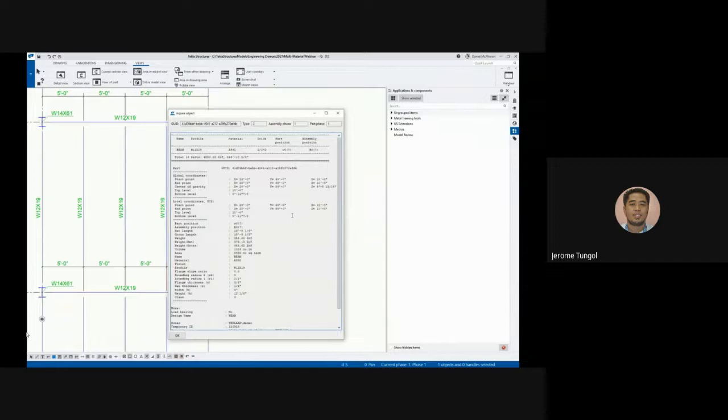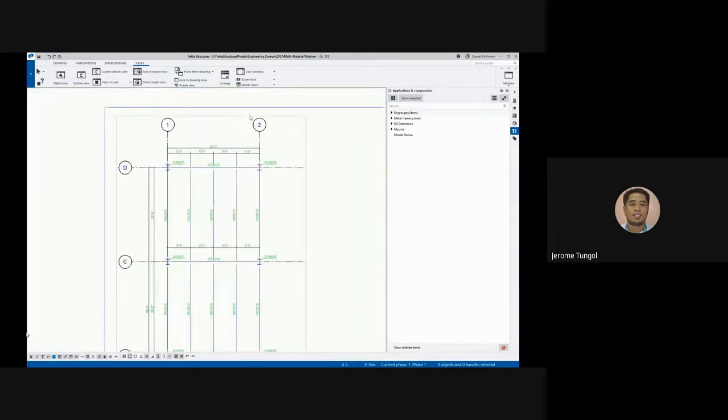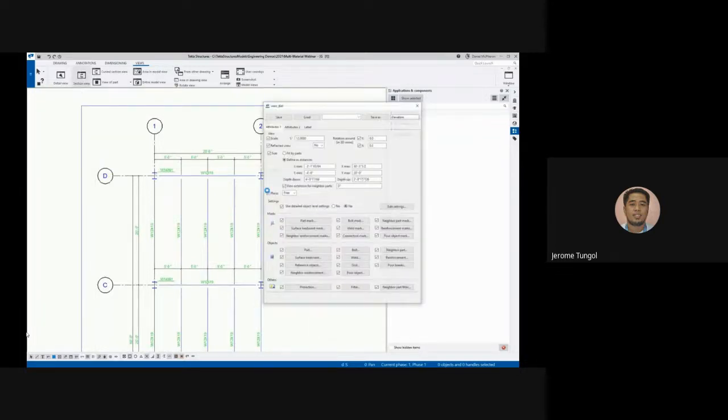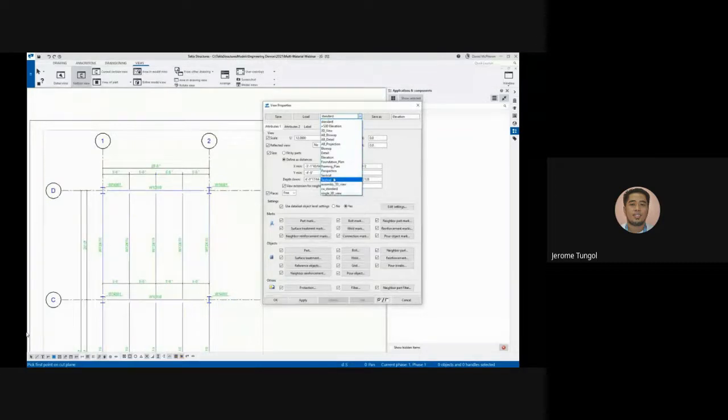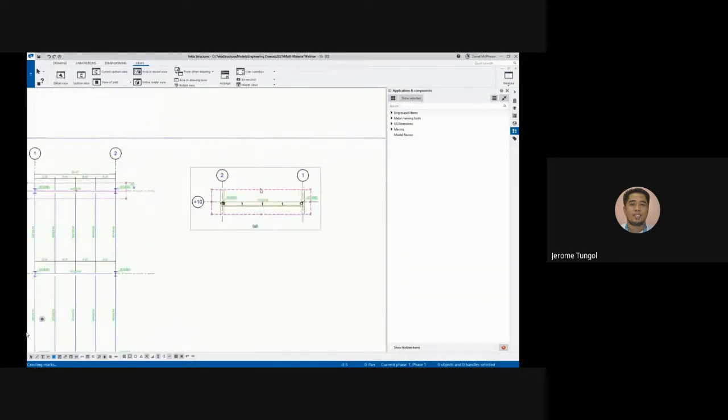And then once you right click the 2D drawing, inquiries of the beams will be shown, such as total volume, area, weight. And then in creating a section view, if you want to view sections in your drawings, just simply click section view and then apply the necessary properties, and then just simply click a location for your section view and then area. And just like that, you have the section drawing.